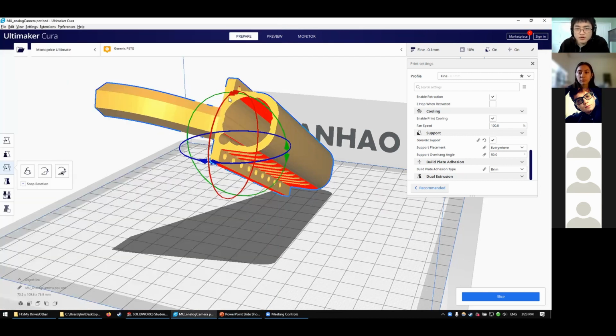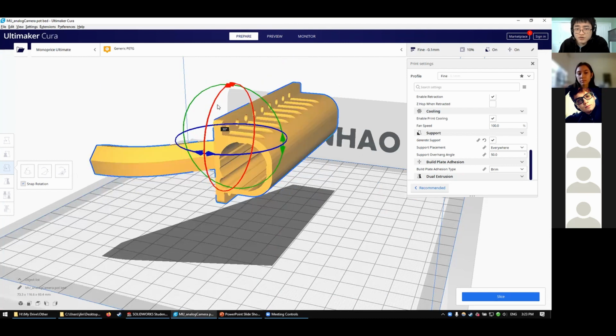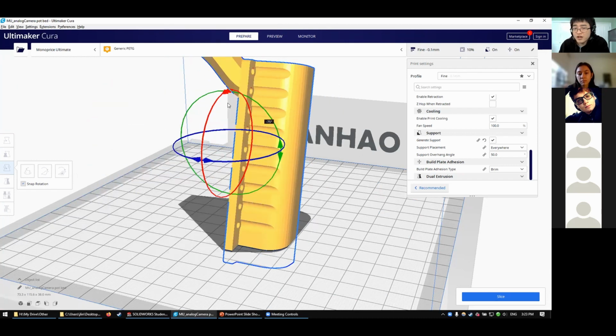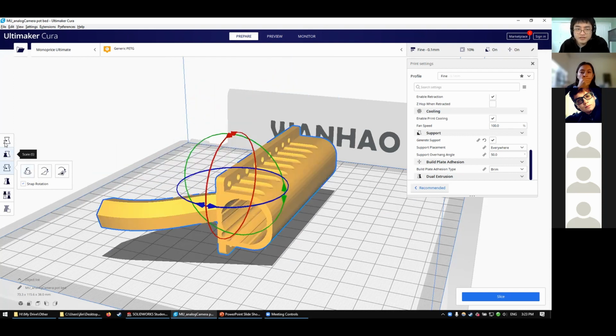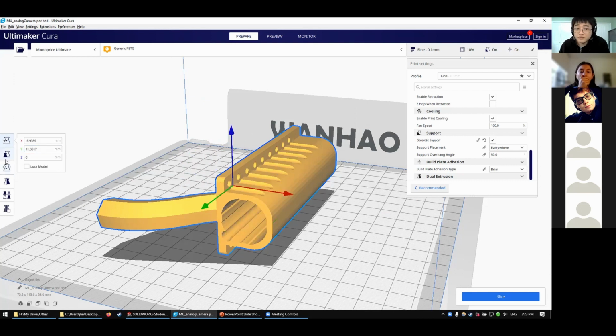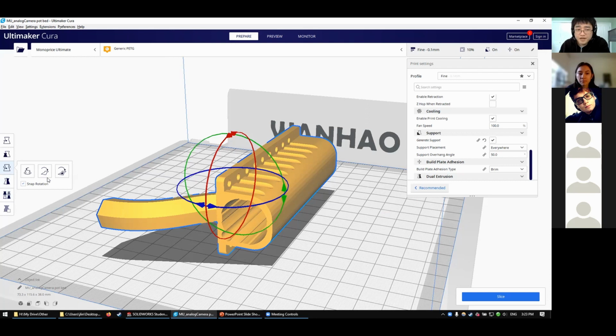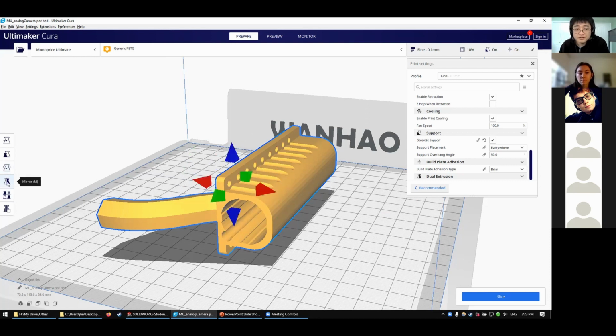Okay. As for using the slicer, most slicers will let you modify or orient the parts you drag and drop into it or open it up with. You see here on the left side, there's a bunch of different buttons. You can move stuff around in X, Y, Z, scale it up or down, rotate it, and have it snap flat. You can also mirror stuff or make copies, I believe, or use some funny options. I haven't used these ones before. This is a new version.